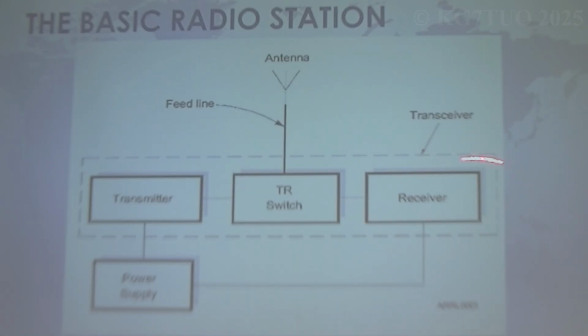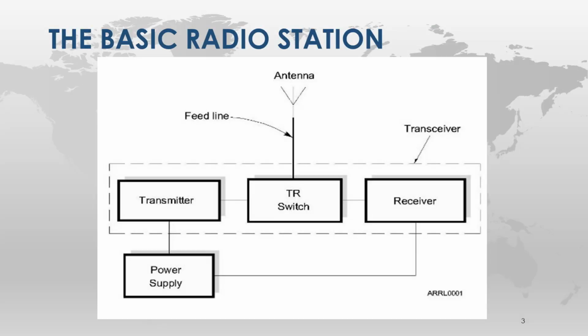Right, so this receiver is looking for millionths and billionths of a volt coming in, and then it jacks up the voltage so it can make an audio signal. Well, this thing's sending out lots and lots of watts. And it's going out the same feed line, so if they're connected, you blow out the IF of the receiver. Even if not connected, just because they're next to each other. Oh, even that. Okay. So you'd have to ground the receiver when the transmitter was on.